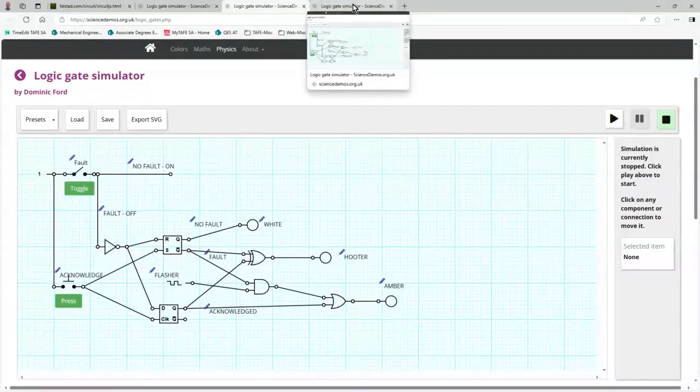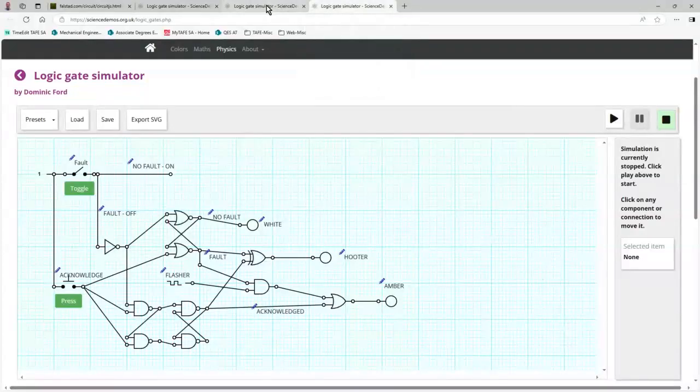So let's have a look at the next one. That one is the same as this one, except it's using just simple gates. Just because it's using simple gates, it doesn't mean it doesn't use latches, because yes, it does. And this is your D latch, those two components. And those four components is a SR latch. Well, actually the other way around. This is SR, this is D. So you can see that you can use basic gates to still create the same environment.